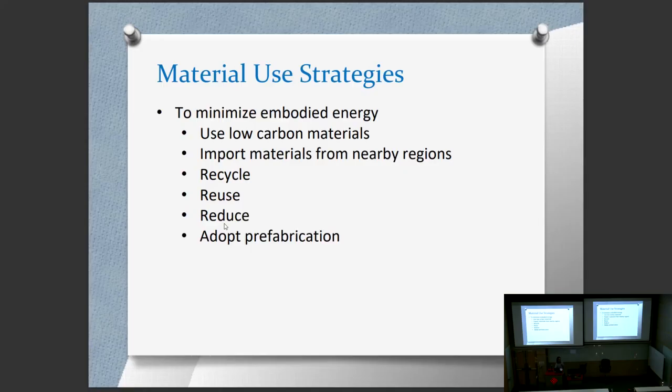If we don't change the design, then it could be quite difficult, so the building design will determine the possibility of reducing the material use. So maybe we can improve the buildability, use some simple design, modular design. For modular design, it will be more probable to reduce the material wastage.